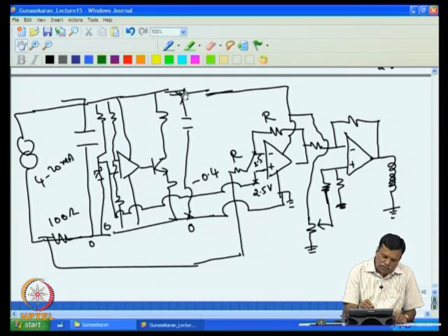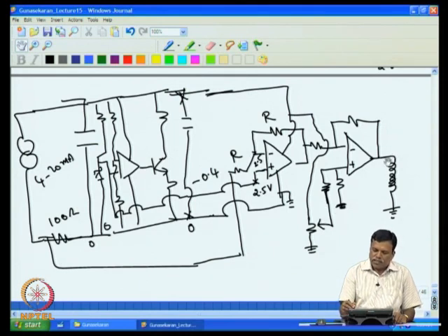Even at 12 milliampere you will have 10 volt, and then corresponding to 12 milliampere you will have 1.2 volt, minus 1.2 volt, that will be converted into plus, and then the difference between these two actually controls the actuator. If this current is more, then obviously the error voltage will be more, because we have set this one, and if the current is more, we want the actuator to move positive, then I can modify even this.